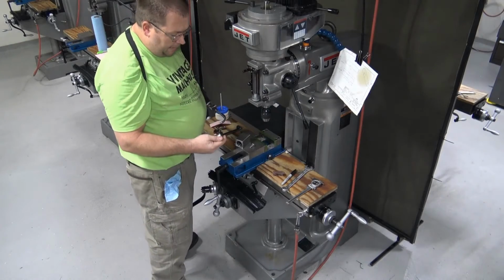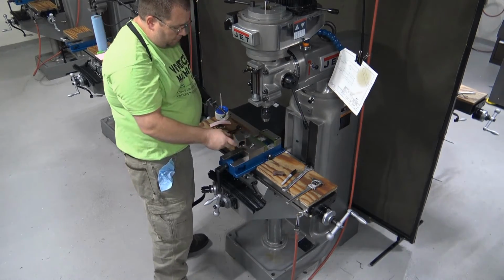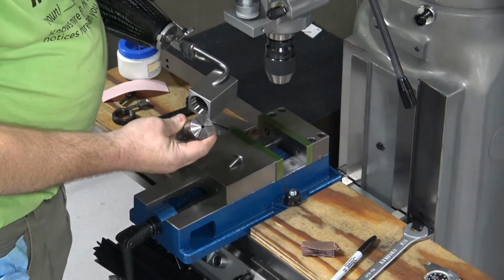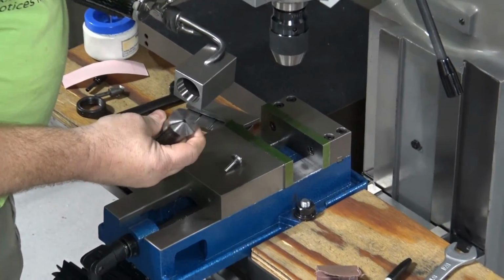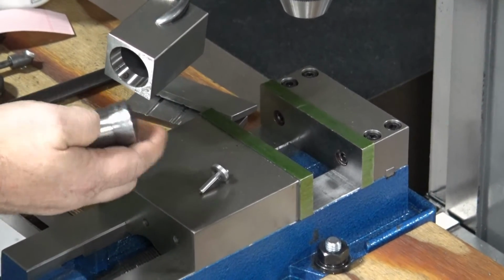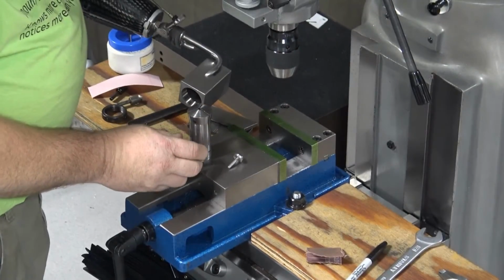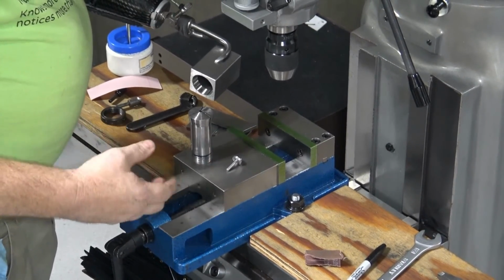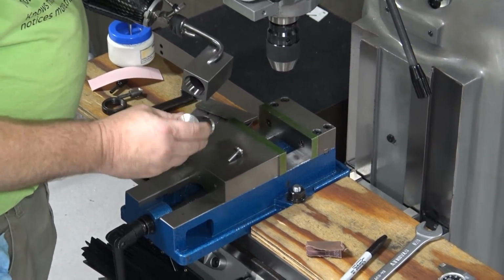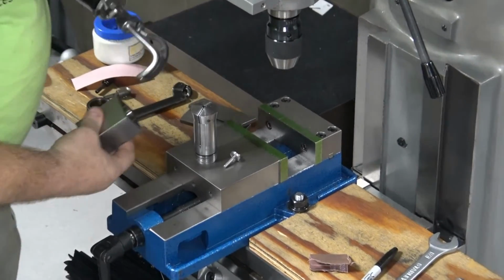We are starting lab number 10. And in the whiteboard talks, we talked about a 5C collet. So this is a standard collet that you would use on a lathe. Most machine guys would understand that this is a lathe collet. The R8 collets, which go up inside the spindle on the milling machine, are a different size and shape, and this style collet's not going to fit up inside that hole. So if you do accidentally pick up the wrong one, you're going to see that it doesn't fit.